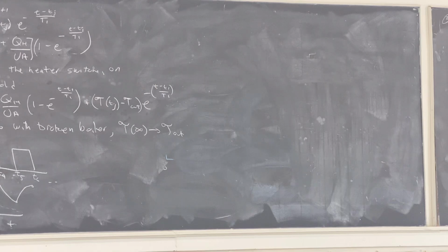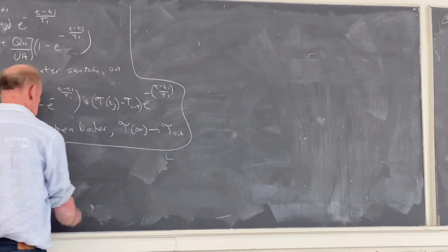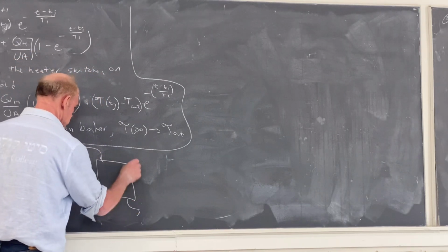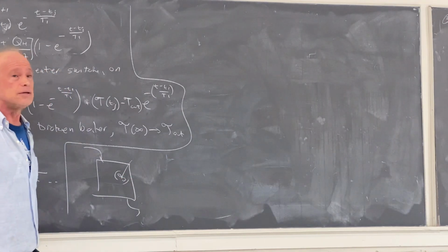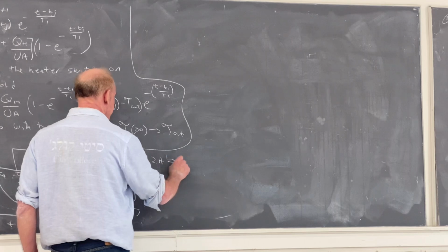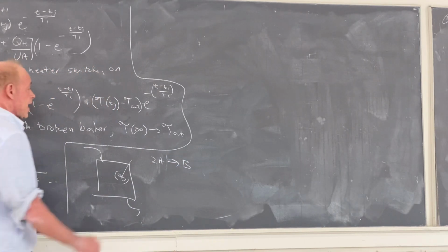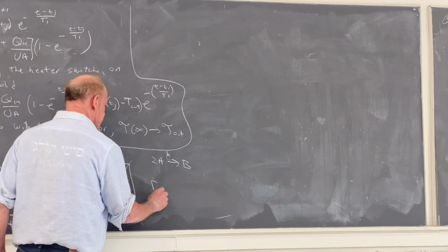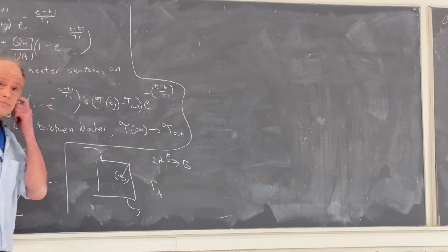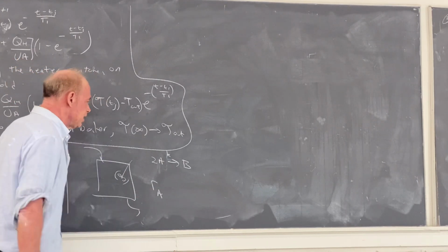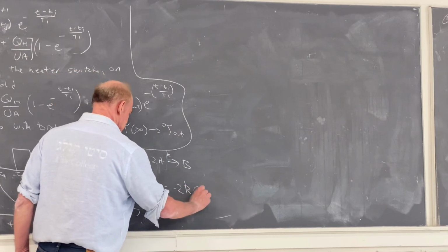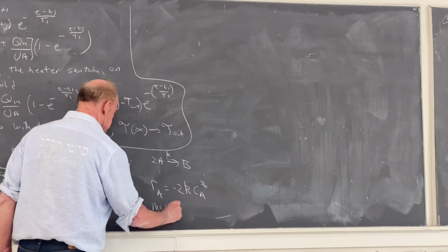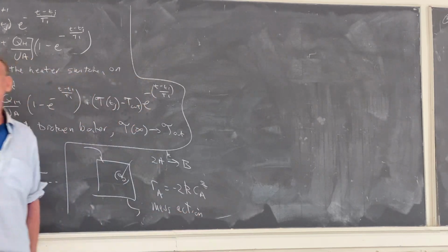So let me give you an example. Let's look at a CSTR where I have a reaction, 2A goes to B. If I have a rate constant K, then the rate of destruction of A, or the rate of production of A, is minus 2K CA squared, if it's mass action kinetics. I assume you've had this already in your kinetics class.